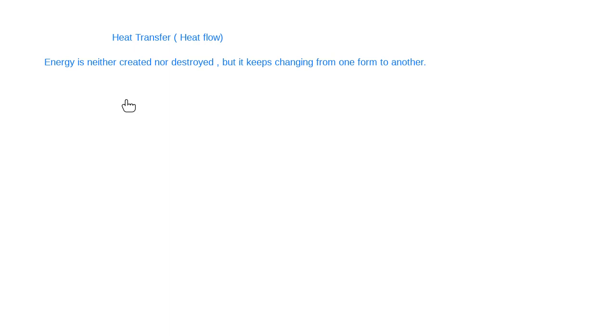When we have an electric motor, the electric energy is converted to mechanical energy. The electric motor rotates the shaft, and the rotation of the shaft is a mechanical energy, and that causes the impeller to rotate as well. The rotation of the impeller, as we have seen before, works on increasing the kinetic energy and the pressure energy of the liquid. And you'll see later on that some of this is actually lost as heat, and that brings us to the definition of efficiency.